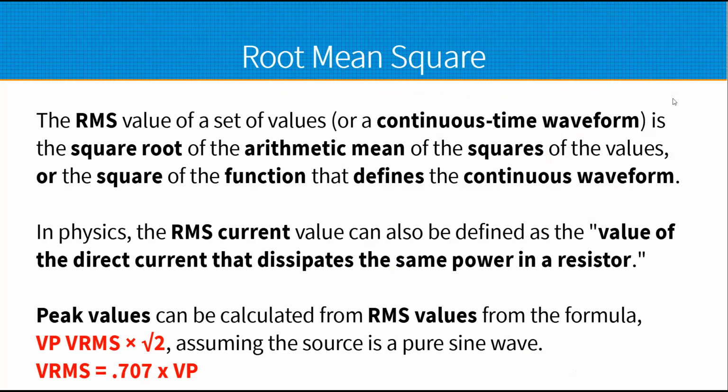Okay. The other thing we didn't talk about was RMS. I think we might have mentioned it, but it's really a way of measuring the equivalent voltage or current of an AC waveform to a DC waveform. So the RMS value of a sinusoidal AC wave is the same value of heat generated by the equivalent DC voltage. So it's essentially the area under the curve.